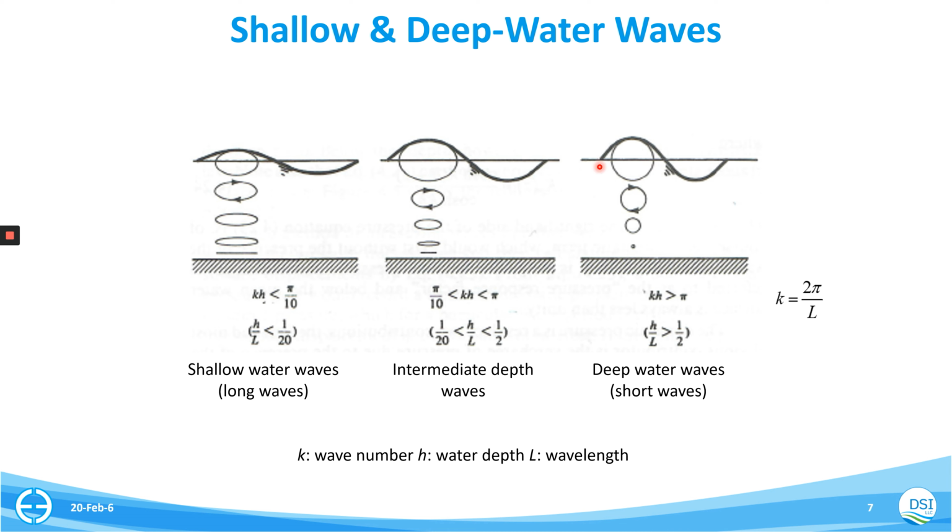These are all derived from linear wave theory, which has lots of limitations and assumptions, such as assuming that water is inviscid, incompressible and irrotational, so that you only see those closed loop motions. But we know that things traveling on the wave can gradually be swashed onto the shore. That's more related to the Stokes drift, which is not a linear process, but a second order or higher order nonlinear process.